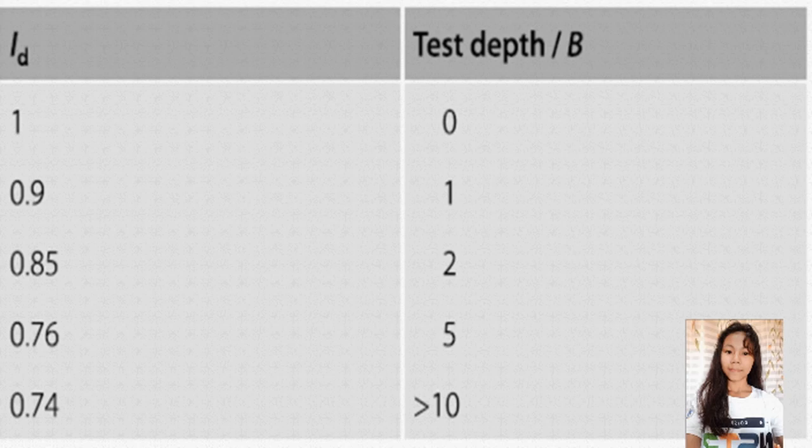The reason for this is that if the shearing jack is horizontal, the spread of shear stress through the sample is not uniform, and failure, that is, the splitting of the sample along the discontinuity, may begin first near to the jack applying shear stress and then proceed away from it. This may cause the sample to ride upwards near the shear jack, with consequent complication to the test result.